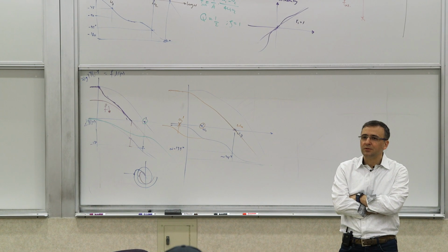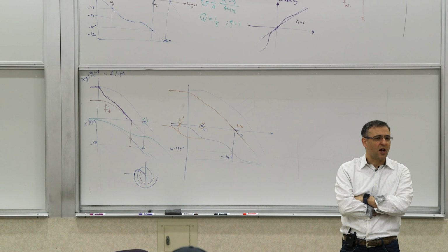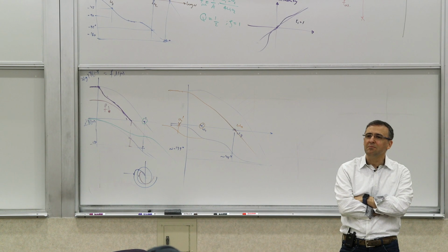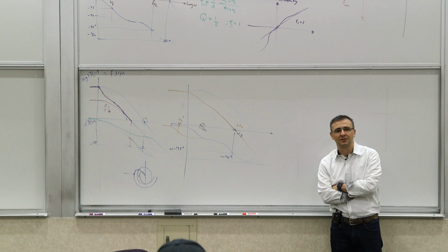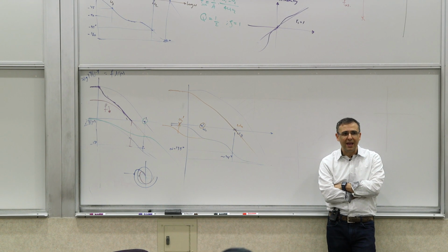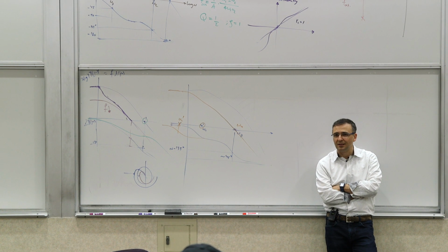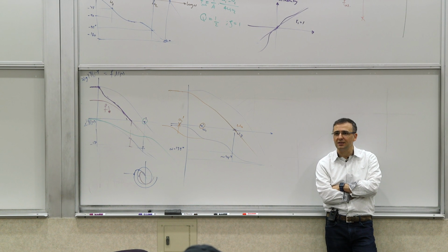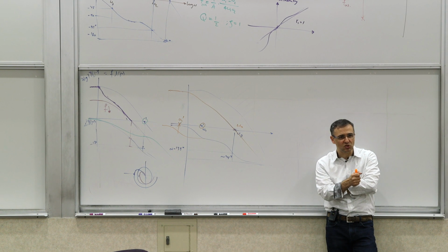So you remember very early on, this was essentially many lectures ago, when we were talking about designing an op-amp, we said we want to minimize the number of stages where we get gain out of. How did we get high gain in the system? The way we got high voltage gain was by generating these nodes that have high impedances and driving them with something, with some drive capability, some gm,